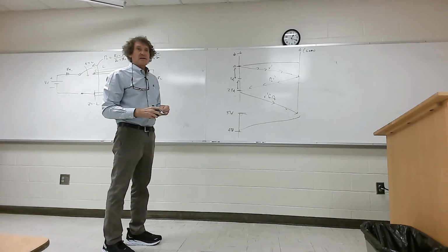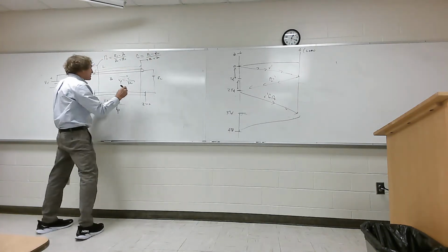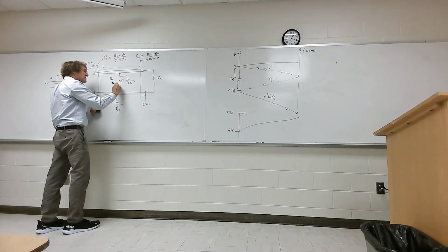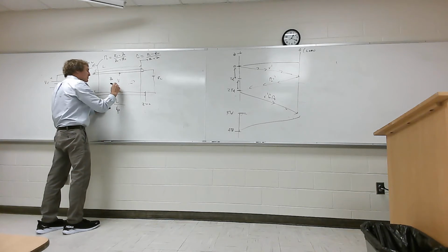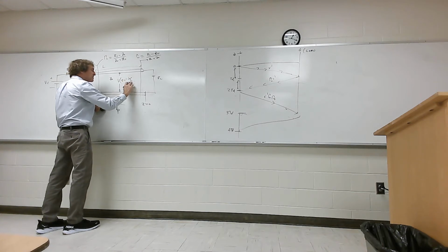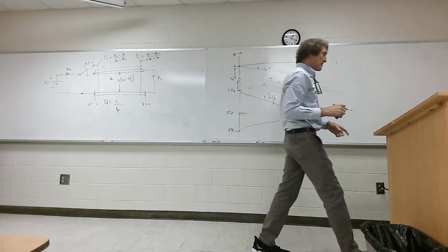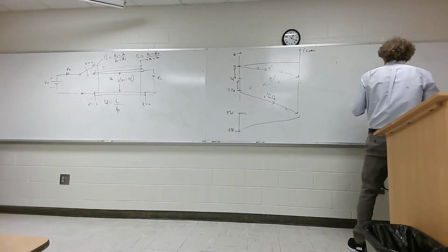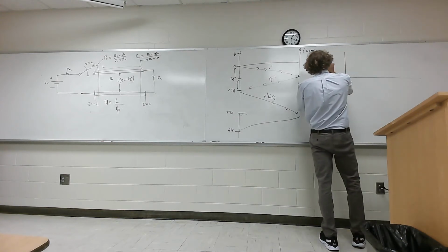Now, if we wanted to get the voltage anywhere on this line, let's just say for now I want the voltage right in the middle of the line, so V at z equals minus L over 2, basically halfway down the line. And I'm going to use this bounce diagram to do it. Here's how it's done. You come over here, and this is going to be the voltage versus time at the distance z equals minus L over 2, halfway down the line.